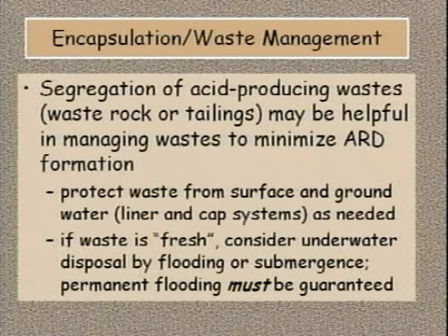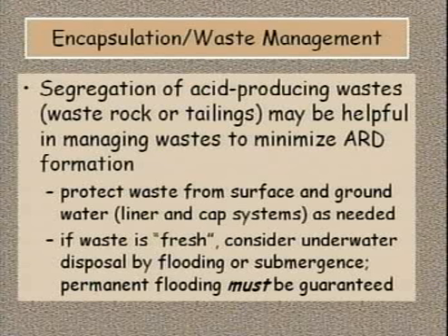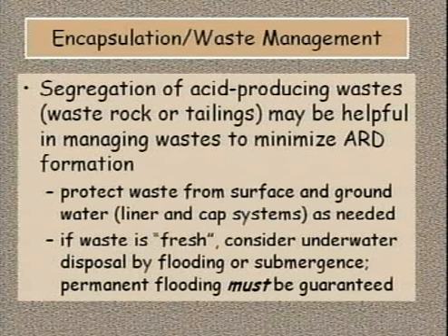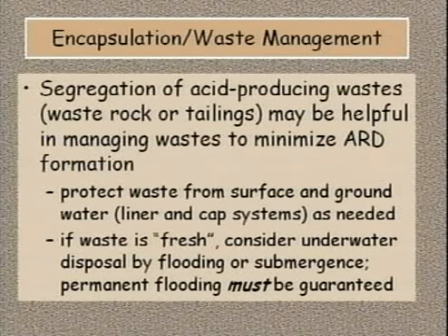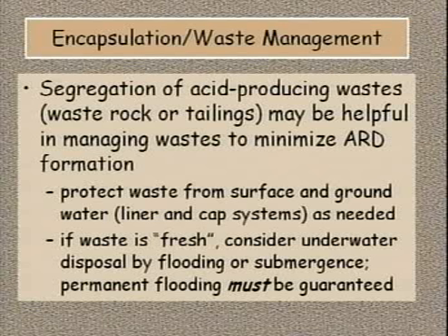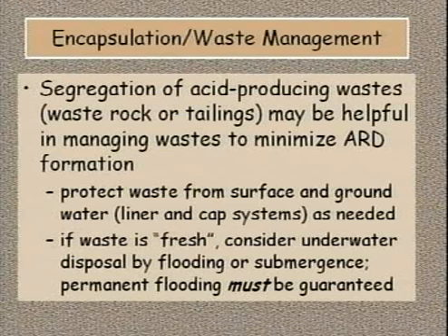But what about abandoned mines? Sometimes reprocessing and remining the waste might yield a saleable byproduct that might offset some of the remediation cost. So once the waste mass is identified, a cap might be constructed over it. If possible, a liner might be used to isolate the waste from the groundwater or vice versa. Flooding of the waste is a viable means of encapsulation. In this case, air contact with the mine waste is avoided. This technique is especially viable for fresh wastes that have not had a chance to oxidize. But for this to work in perpetuity, total and permanent submergence is required.